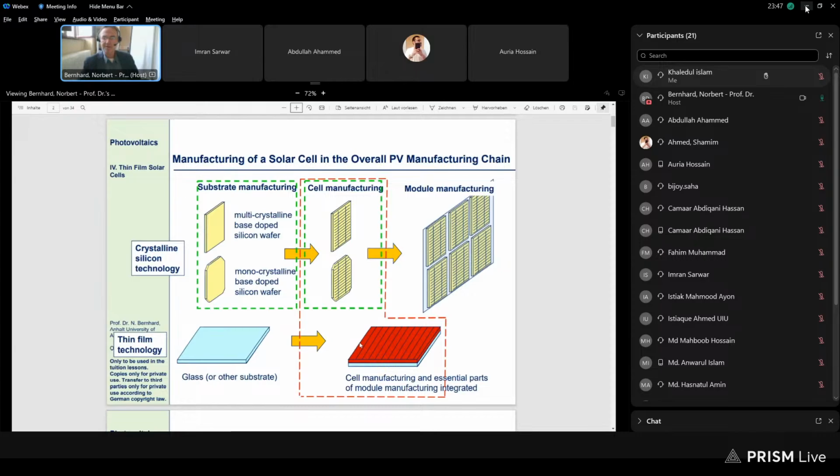And of course, one could now think that this step is an obstacle for the electrons going to the right contact, because the electrons have to go to the left and the holes have to go to the right. But you see, this is at most 100 milli-electron volts. The average thermal energy, which is roughly in the range of kT, at room temperature is 25 milli-electron volts.